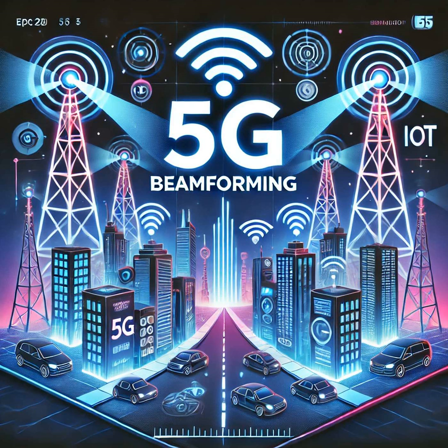On the other side, at 30 gigahertz, which is a centimeter wave, that is 1 centimeter, the half wavelength is only 5 millimeter. Therefore, as frequency increases, the size of each antenna element decreases. The smaller size at higher frequency makes it feasible to include an antenna array within the user equipment or mobile.